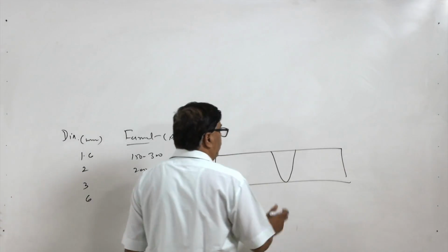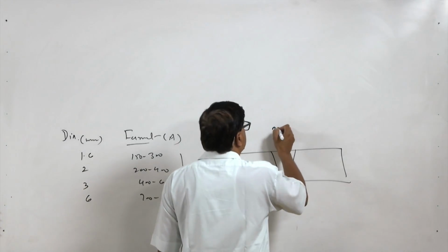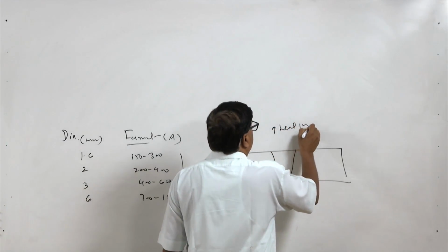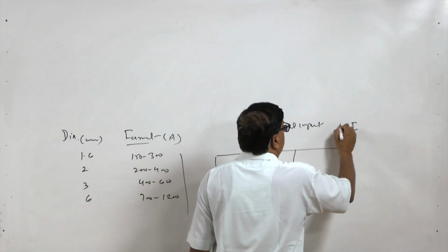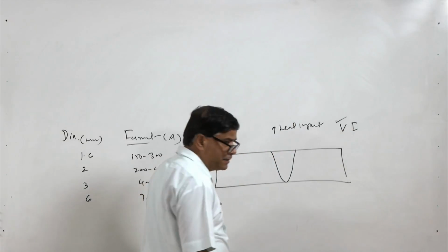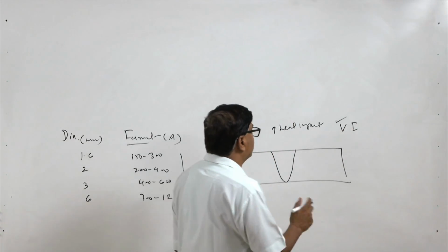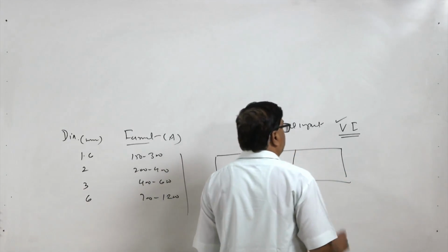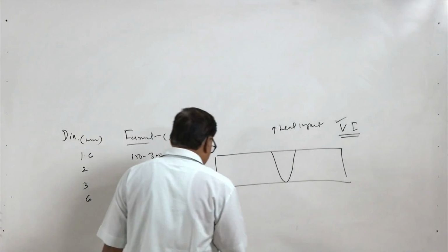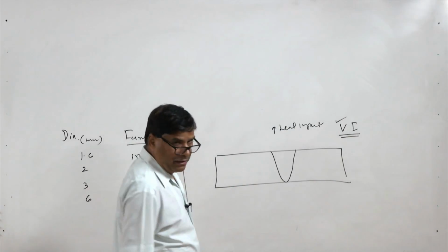So, for increasing the heat input, we need to generate a lot of heat. Heat is not actually generated by increasing the arc voltage, but simply by increasing the current, and to increase the current we have to select larger diameter electrodes.